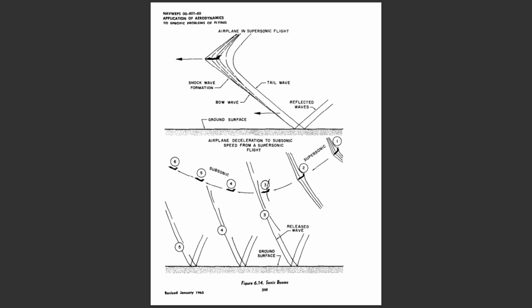The characteristics of the airplane generating the shock waves will be of some importance, since a large, high-drag, high gross weight airplane in flight at high Mach number will be transferring greater energy to the air mass. Flight altitude will have an important bearing on boom intensity, since at high altitude the pressure jump across a given waveform is much less. In addition, at high altitude, a greater distance exists between the generating source of the pressure disturbance and the ground level, and the strength of the wave will have a greater distance in which to decay. The ordinary variation of temperature and density plus the natural turbulence of atmosphere will tend to reflect or dissipate the shock wave generated at high altitude.